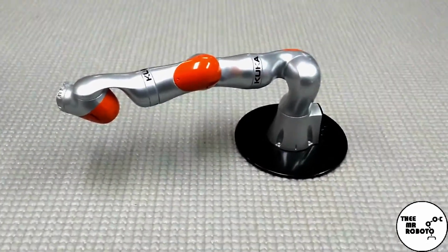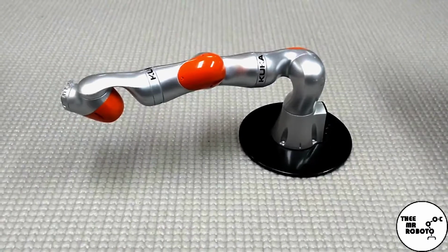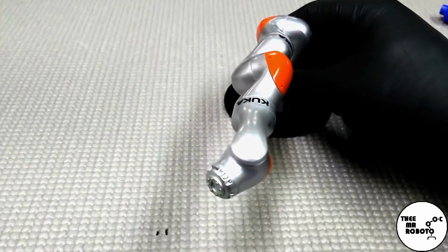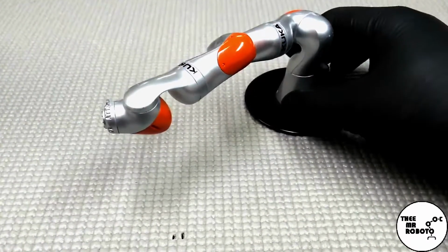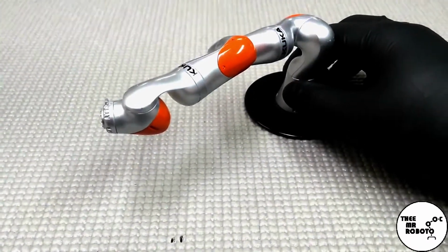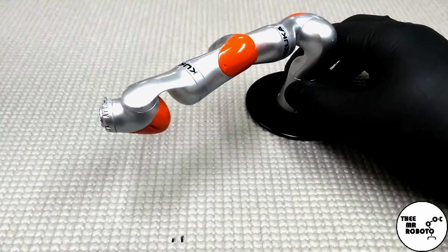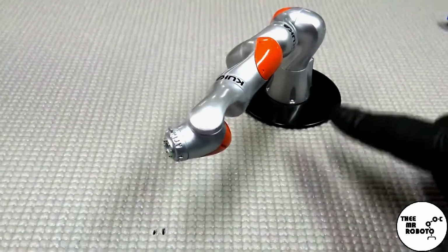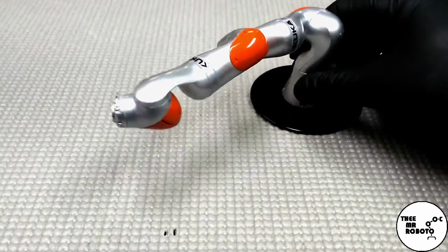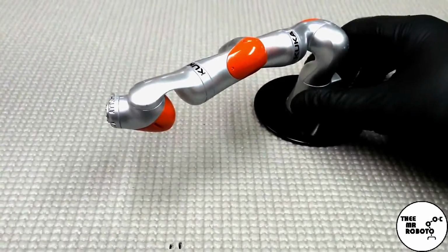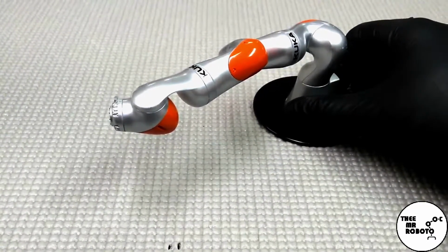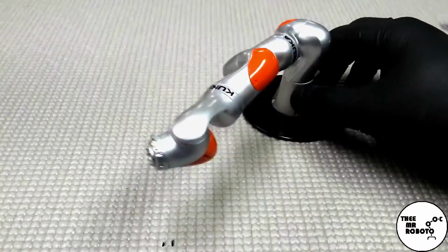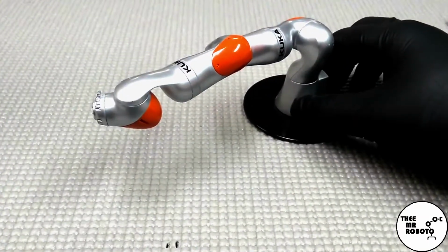The kinematic equations that drive the axes of this robot are simplified down to this XYZ relationship between these two coordinate systems. So these native coordinate systems are the bare minimum of what you need to program a robot as far as the path of the robot.